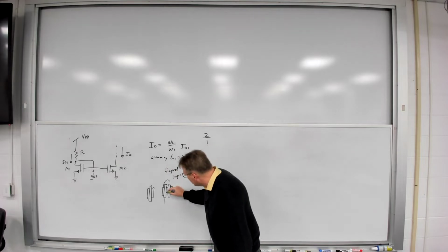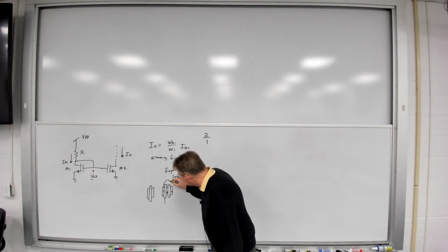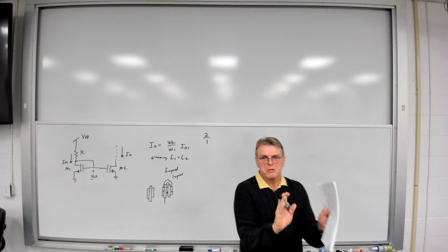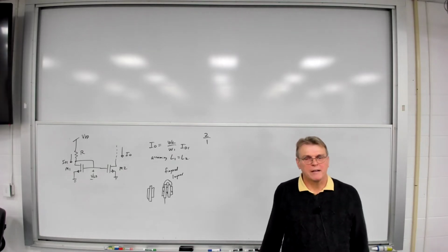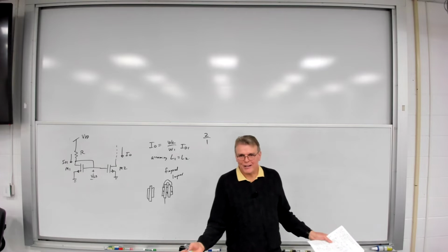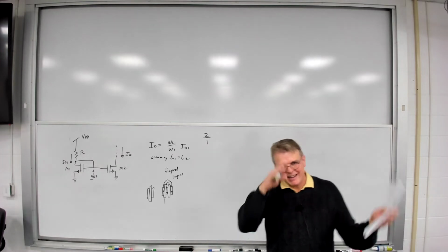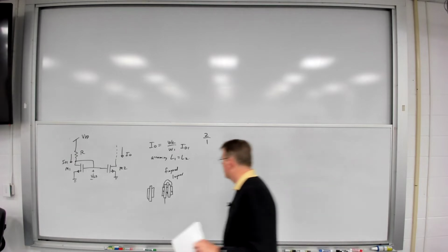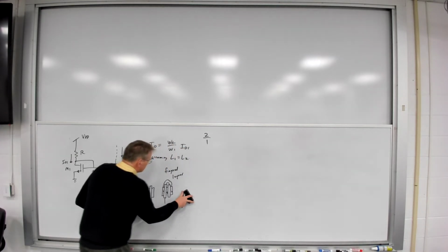So for example, that'll be the drain. These will be the source diffusions, and so they'll connect the sources together, they'll connect the gates together. And since they merge the diffusions together, they create a common drain. So this is very common layout stuff. And although this is not a layout class, I wanted you guys to understand how engineers think when they're doing the layouts for these types of circuits. All right?